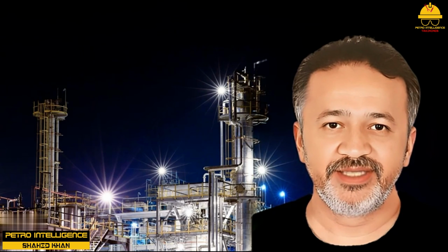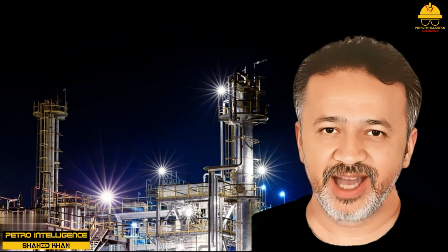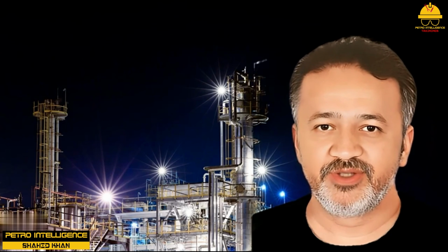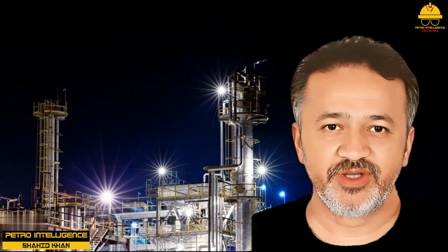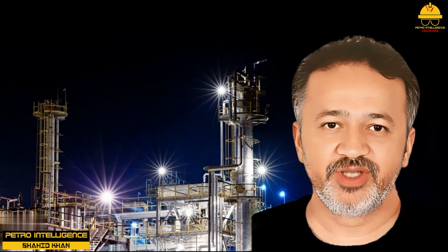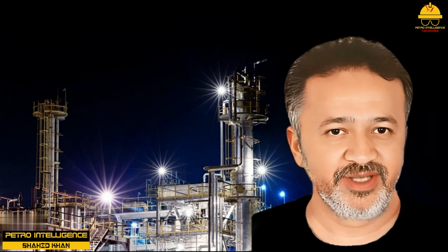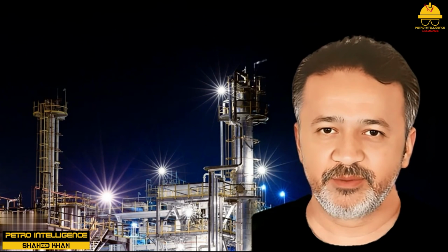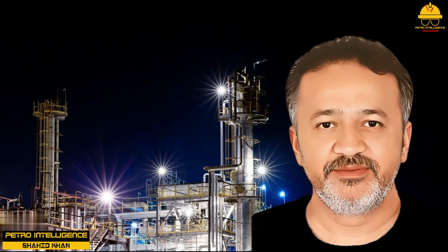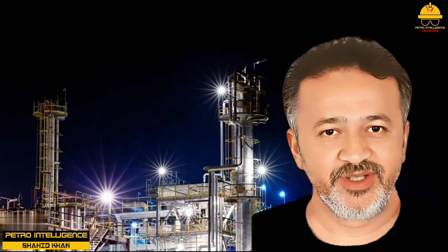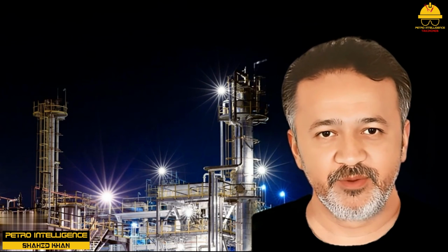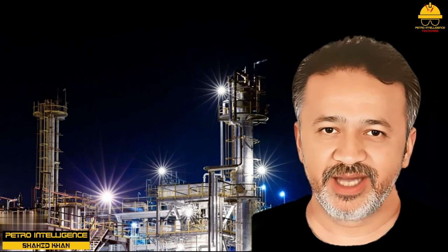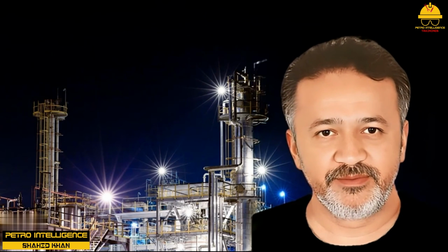There are 5 basic types of reactors: stirred tank reactors, converters or fixed bed reactors, fluidized bed reactors, tubular reactors, and furnaces. Alkylation units take 2 small molecules and combine them into 1 large molecule. Exothermic reactions give off heat. Endothermic reactions absorb heat. Replacement reactions can be used to remove undesired products and replace them with desired ones.